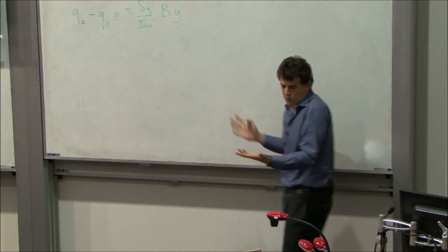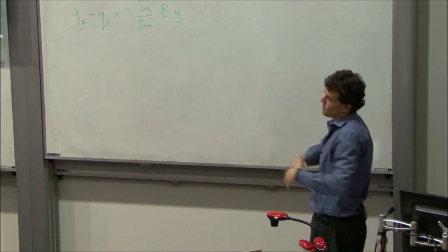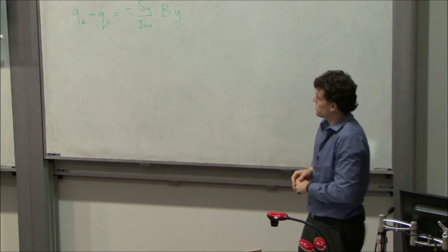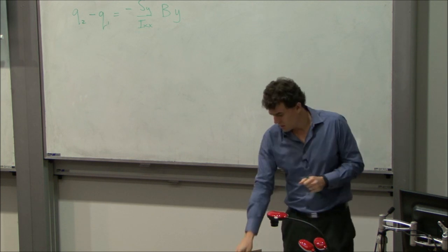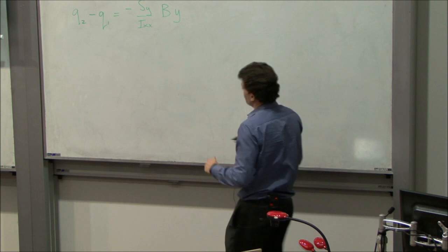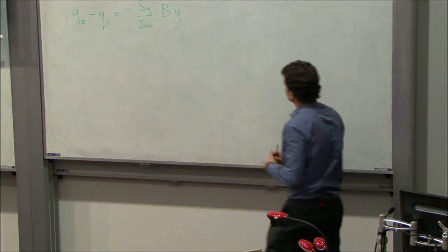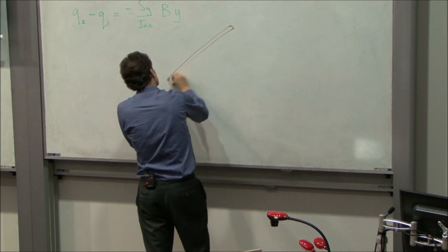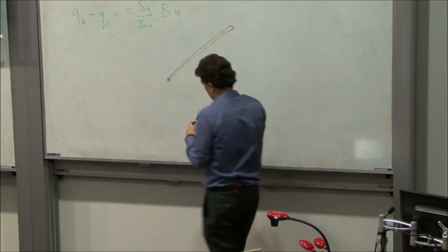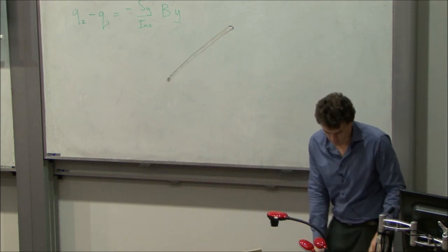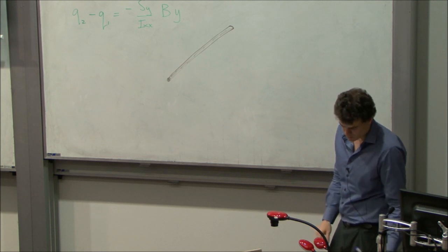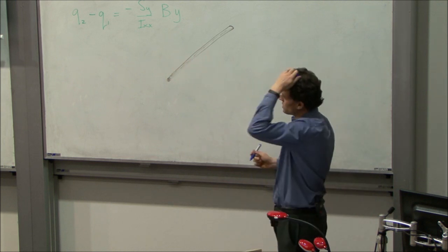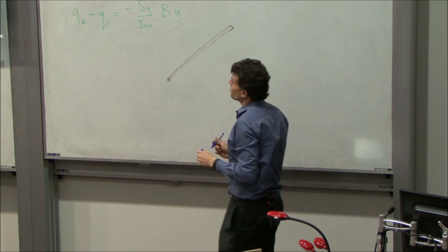Now we've got a third shear flow in there. We've got some other part that we have to add into the equilibrium, and technically we could have 4 or 5 or 6 shear flows all acting on the same boom if we had a very complex structure, but in practice 3 is the most we ever have to deal with. If we take the boom by itself, acting on the boom according to our diagram up there, and I'll use the notation that I've got up there just so that we can follow along.